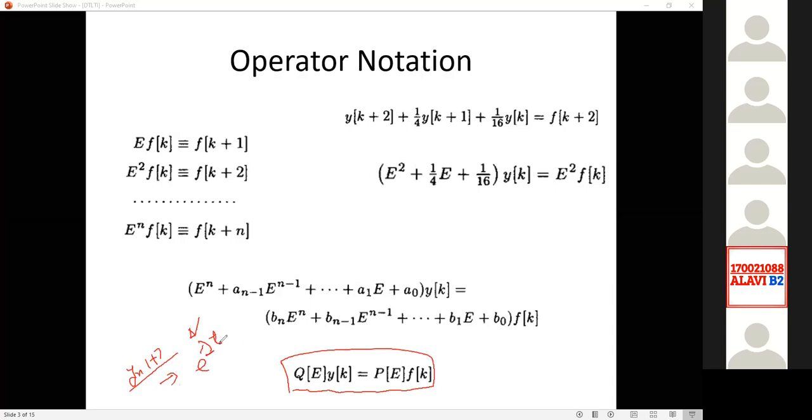For a higher order system, if it is complex conjugate, then the real part should be negative. But if some real part becomes positive, then your system becomes unstable, okay? But if your system is unstable, we still have some technique to bring it to the stable region, and I hope you will learn it more elaborately in your control course.